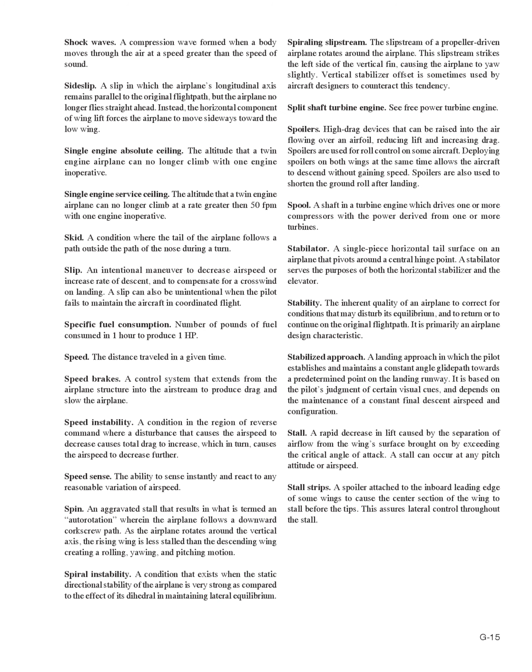Shock waves. A compression wave formed when a body moves through the air at a speed greater than the speed of sound. Side slip. A slip in which the airplane's longitudinal axis remains parallel to the original flight path, but the airplane no longer flies straight ahead. Instead, the horizontal component of wing lift forces the airplane to move sideways toward the low wing.